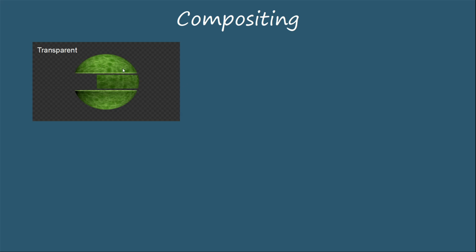I already talked about the almost orthographic view of the 3D logo at the end of the animation, as you can see here. As explained, to achieve this, I changed the focal length of the camera from 35 to 100 millimeter. This is basically a camera zoom into the picture. And at the same time, I moved the camera away from the 3D logo, and these two effects caused this change from a perspective to an orthographic view of the logo.